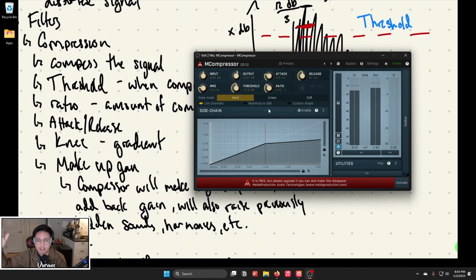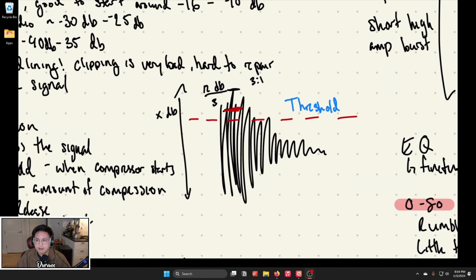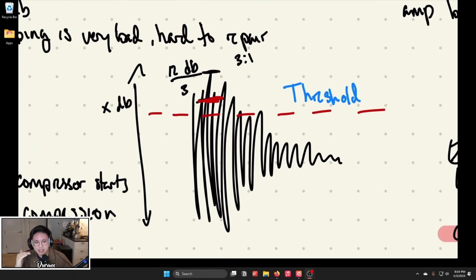And then the same thing, it's like a gradient all the way up and down. So it helps to make your compressor sound more natural. And then the last part of a compressor is the makeup gain, which is essentially this output. By the science of a compressor, you're compressing these waveforms down, which means you're actually decreasing the volume of these waveforms. So you're actually losing gain by doing so. So the makeup gain is essentially adding more gain back to your signal after it's been compressed.